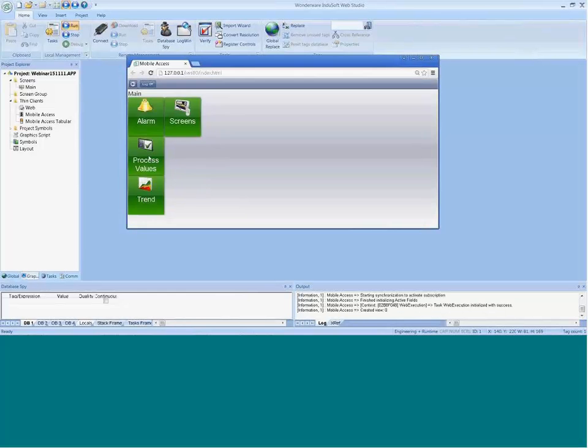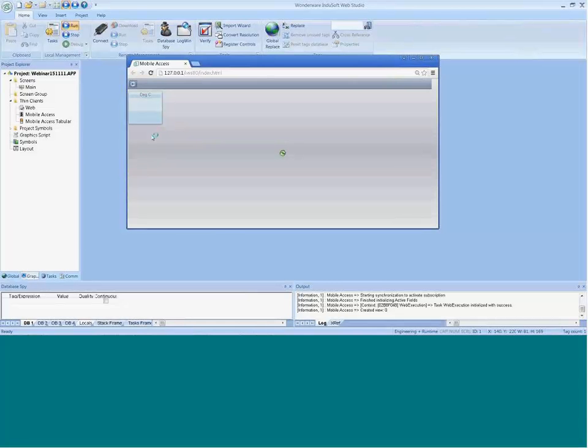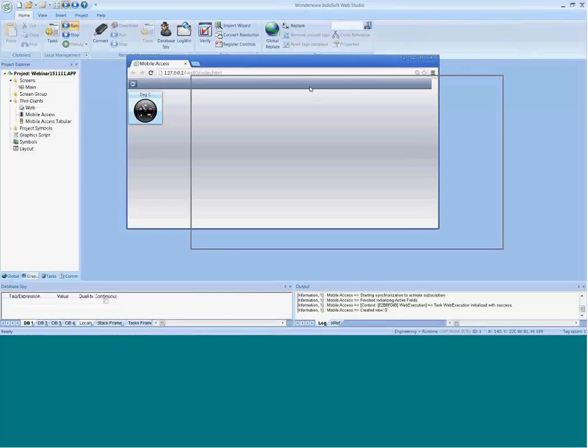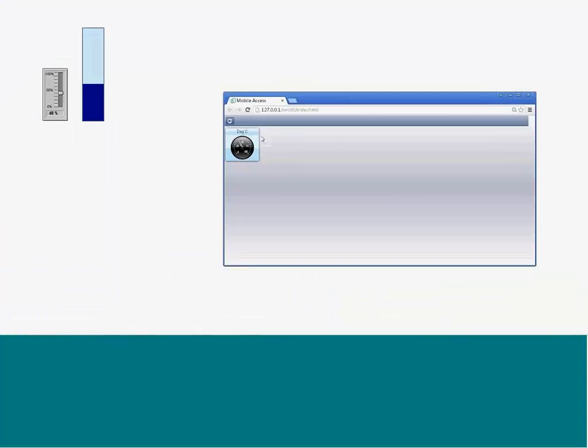Now, the first thing that I enabled was the ability to see this as a gauge. So here's my degree C that I set up, and you can see the value there. If I keep this in the forefront, keep my project here, you can see that the value there is 40. If I go and click on this, I can either type in this box down here, or I can change the set point here and then write that back. You can see on the application over here that it's written that.